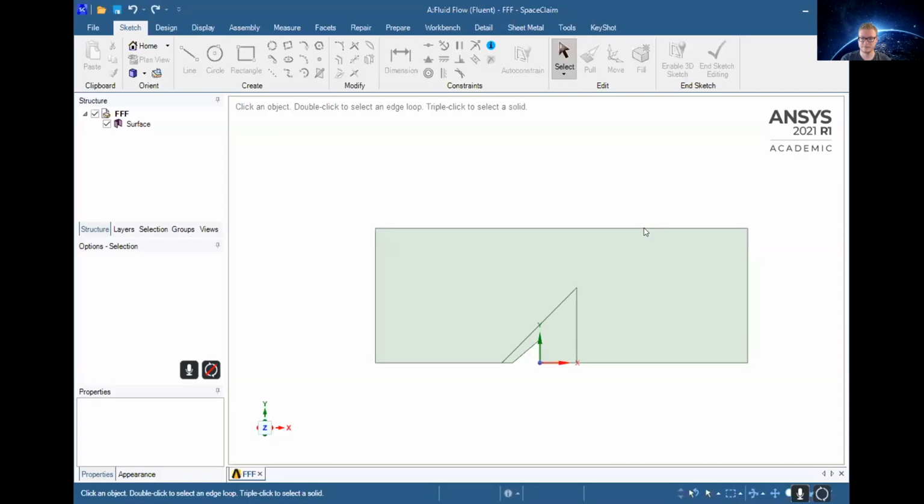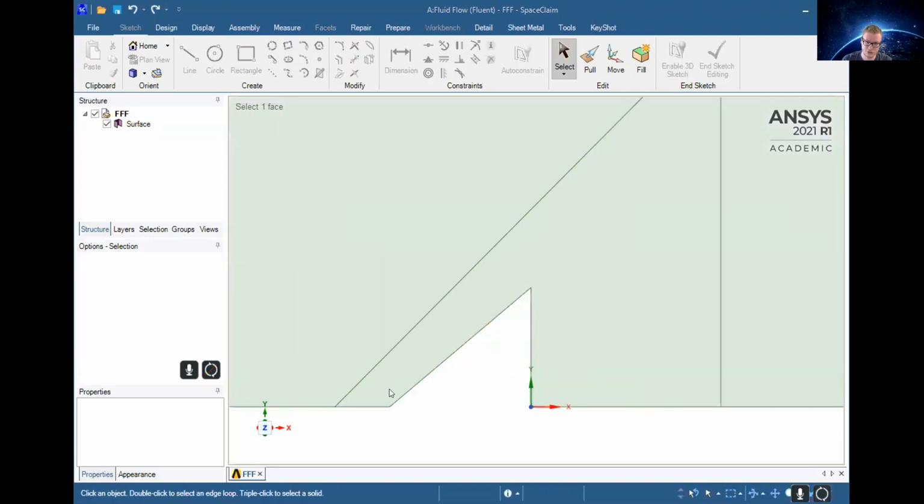We're going to focus on drawing a perfect triangle. We're going to start with half of it. All right, so we got it nice and loaded. You're going to start off by drawing half a triangle. In our case, the back of our triangle is going to be about 30 centimeters, so we're going to half it and do it by 15 centimeters. And we want an angle of 45 degrees. So you want that right here. And then it'll automatically calculate the length needed to get a 45-degree angle,